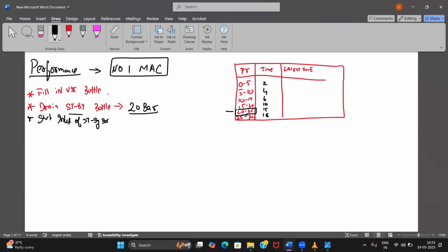Sir, there are also equalizing valves, right? Can we close those first? Keep the closing valve in your main air bottle. Equalizing valve. Okay. If you open the inlet valve, that is filling, that is only the equalizing valve. The inlet valve functions as the equalizing valve only. If you open both inlet valves, it will equalize the pressure. Have you seen that? Yes sir.